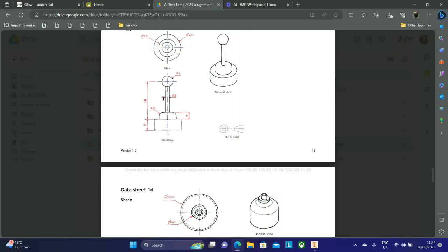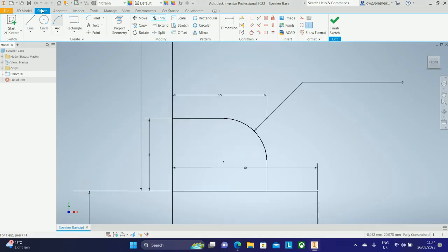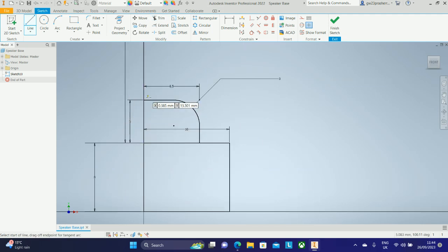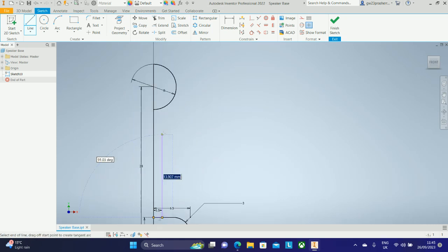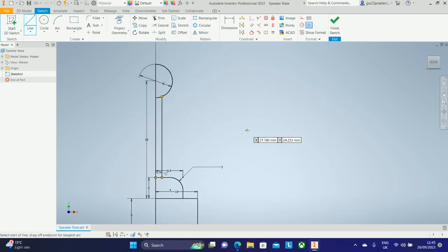Now we can see that the stem part of the toggle switch is a circle again, but it has a diameter of 3, so we're going to have to draw a thickness of 1.5. So I'm going to go down into the top of my 5 line. There's my original 8, and there's my 5, and I'm going to go along my 6.5 line 1.5. Then I'm going to bring this line up until it touches my circle, like so.